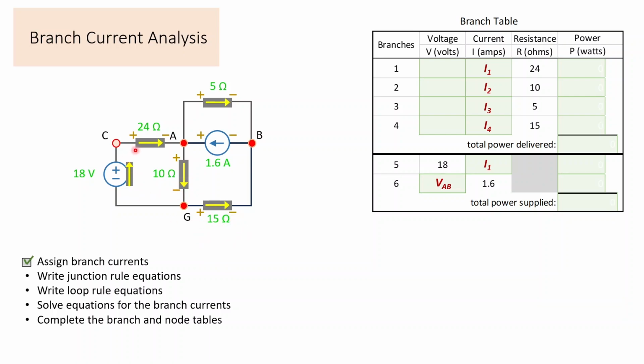If we assume the flow, for example, in the 24 ohms is to the right, then the Ohm's law of volts, V equals IR, is a voltage drop. So the volts goes plus to minus. We decrease in volts going with the flow, whereas we expect for power supplies the volts to increase as we go with the flow.